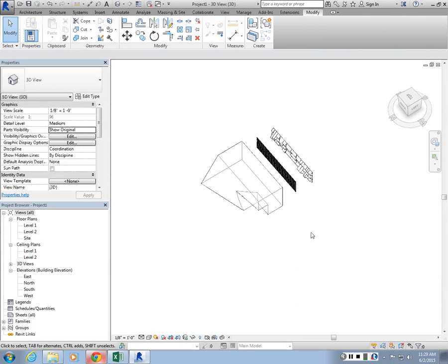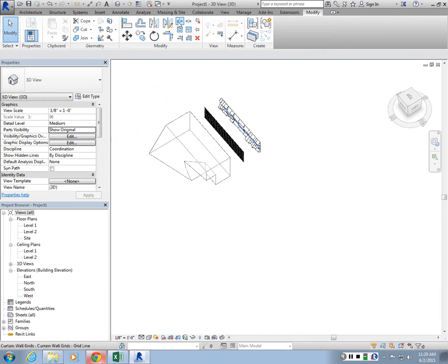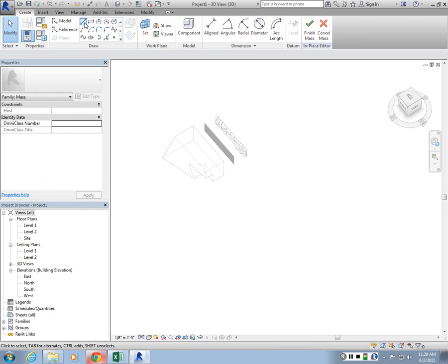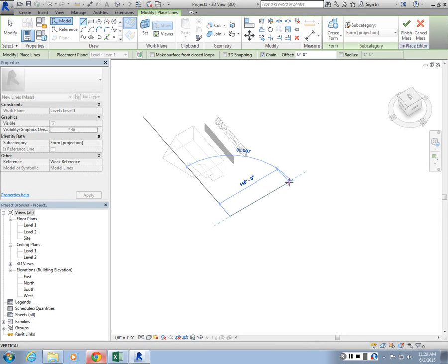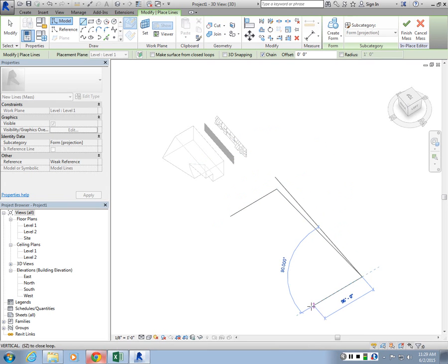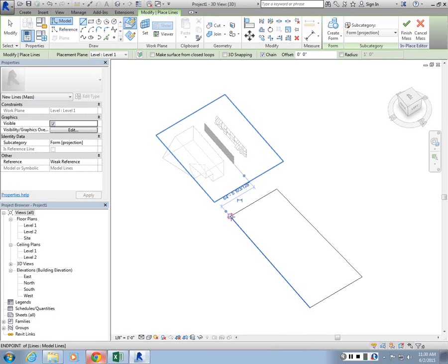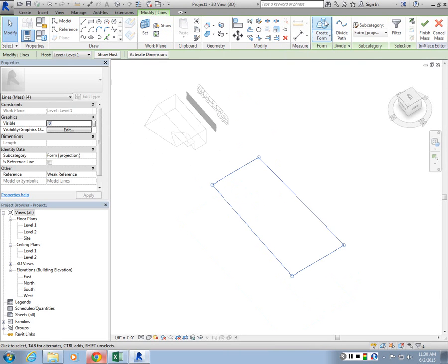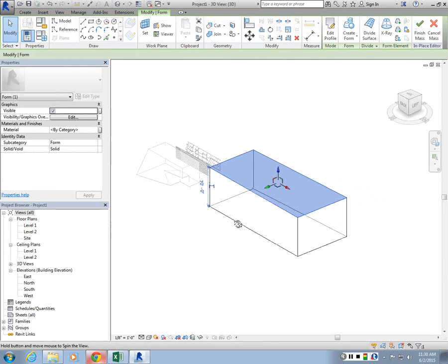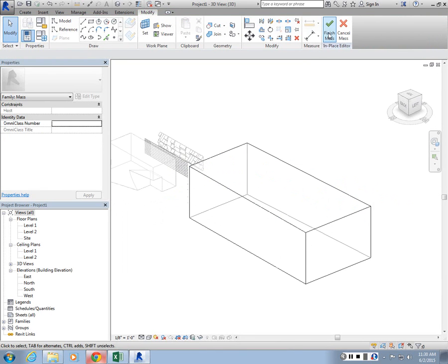Now, one of the simplest ways you can approach using the massing tool is to, let's say, create an undulating surface like the precedents I've been showing you. Let me show you how you can do something like that. So I'm going to go to Massing Insight again and make another In-place Mass. And this time, let's say we want to define a block that is the dimension of our massing. And then I'm going to do create form. And let's say the height is going to be 70 feet. Well, this is a big block, right? I'm going to do finish mass for now.